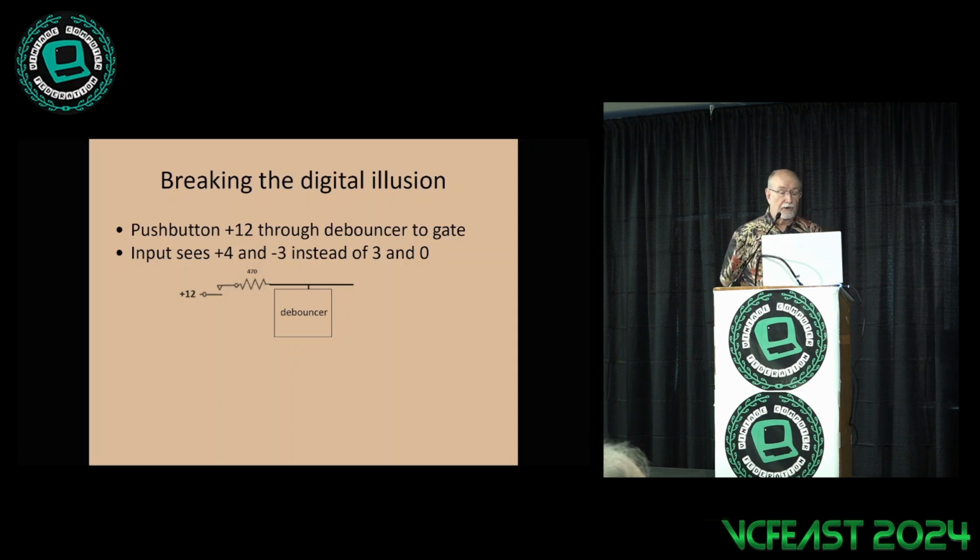Another one that frustrated somebody else is they saw a push button coming into the computer. Now, a number of you, if you do design work, you know what a metastable state is with gates. So if you send signals into our normal modern clock system, sometimes it won't quite go to 0 or 1, and it takes a few cycles, which is why you'll see a chain of flip-flops to introduce an external signal in so you can get it synchronized to the clock. Otherwise, this wacky thing happens. Luckily, it doesn't have to happen with IBM because they're not a clock system.